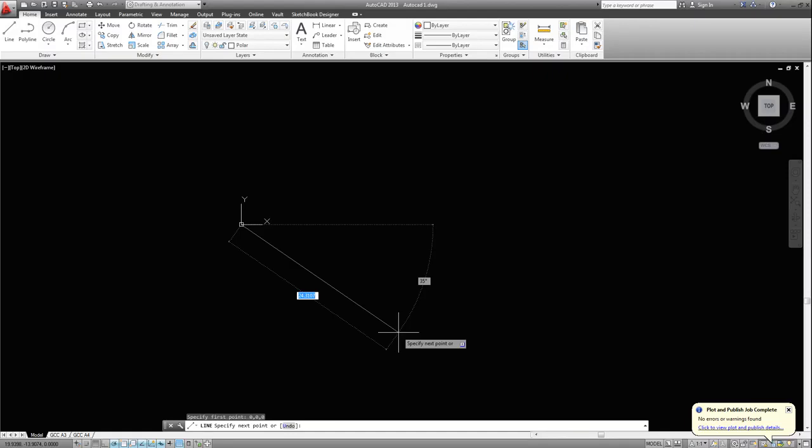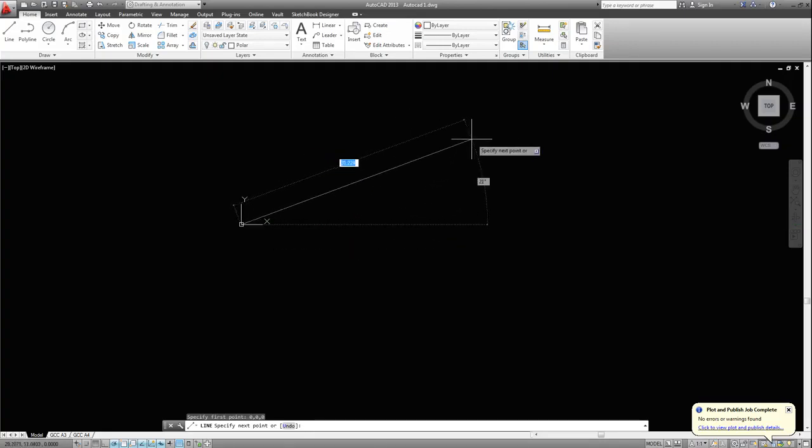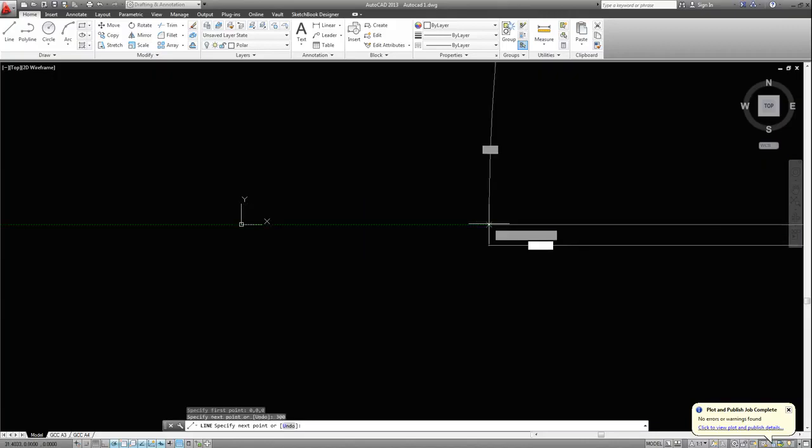Because we're working two-dimensionally, you still put Z in as 0, but it will always be 0. It would only be something different if we were working in 3 dimensions, but we're not doing that. We're only working in 2 dimensions. So then you can just specify however long the line is that you want. When it's on 0 there, all we need to do is type our dimension in, but you've always got to give it a dimension.